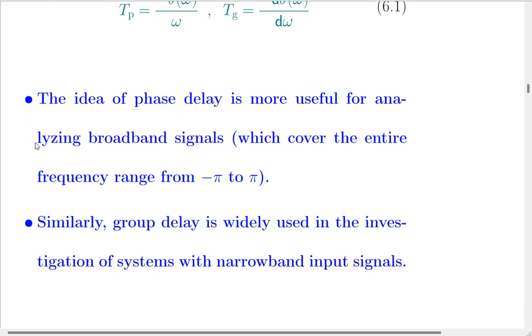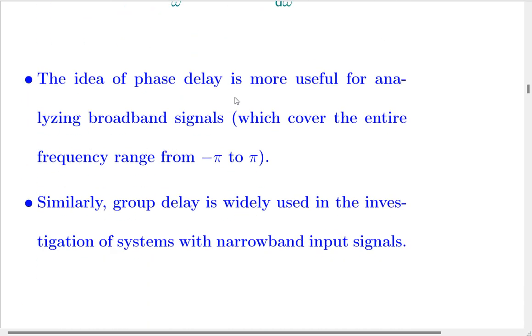Right. The idea of phase delay is more useful for analyzing broadband signals which cover the entire frequency range from minus pi up to pi. Similarly, group delay is widely used in the investigation of systems with narrowband input signals.